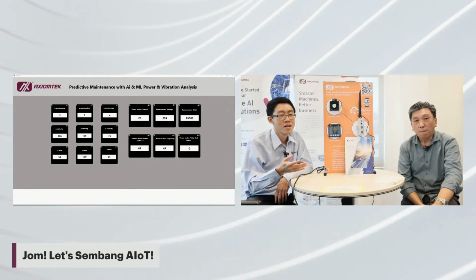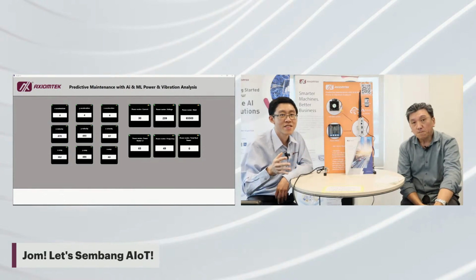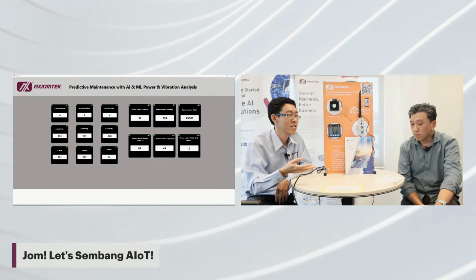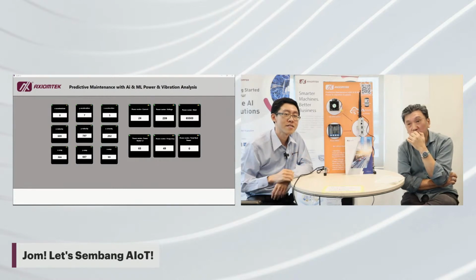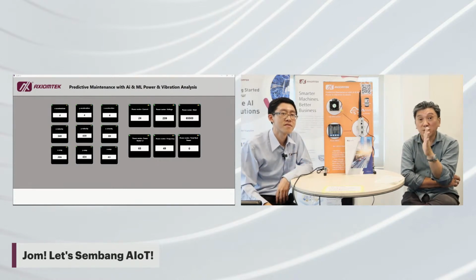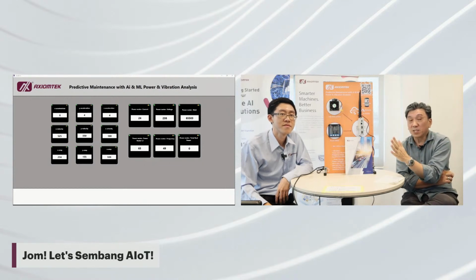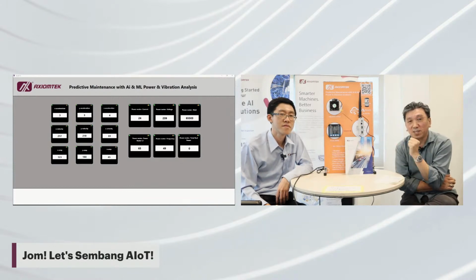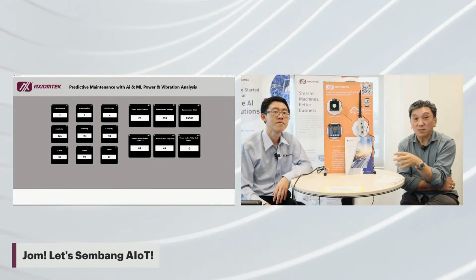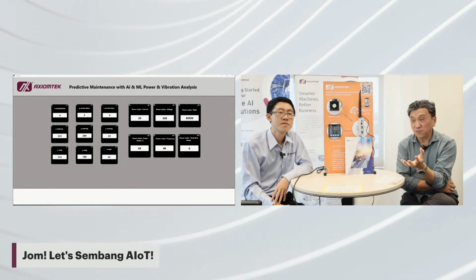Preventive maintenance means you do a scheduled maintenance, so maybe every 1 month you carry out the maintenance. But for predictive maintenance, you require an AI to tell you when you need to start carrying out the maintenance, depending on the sensor data. So the difference is, preventive maintenance is scheduled, while predictive maintenance is data driven, meaning you are driven by the data when to perform the maintenance. That's supposed to be more efficient or effective in terms of cost, time or effort that you are putting in.